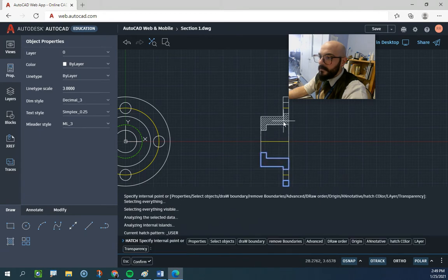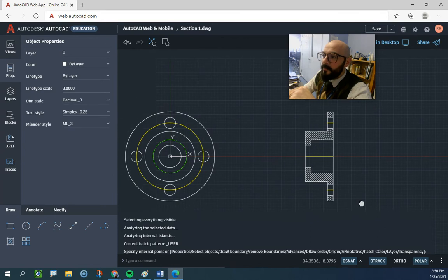Great. Now I'm going to select all the areas. So I click, click, and click. All of these are now selected. It even gives me a preview. Once I have everything the way I want it, and I have all my parts selected, I'm just going to confirm. And I have now produced a hatch that is going to represent any of the cut material.